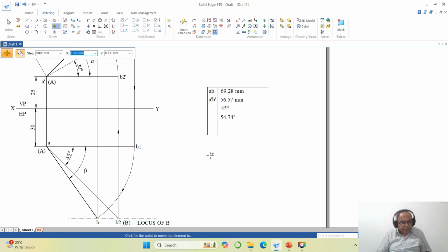Move, the displacement in this direction is 0, okay, 0. So you take this and you take this, okay. Next, go to move, again you take this. Now the x displacement is 0, x displacement is 0 because you are moving in the vertical direction, okay.